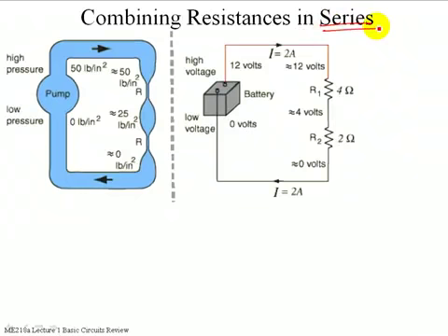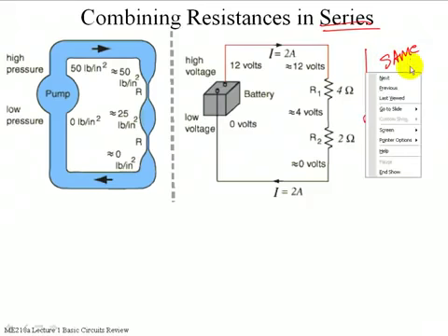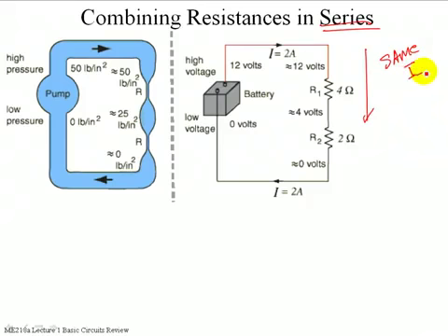So once again, what does it mean for two things to be in series? Yep, same current. Same current has to be flowing through both devices for them to be considered in series. So how do we go about figuring out the equivalent resistance of two resistors in series?